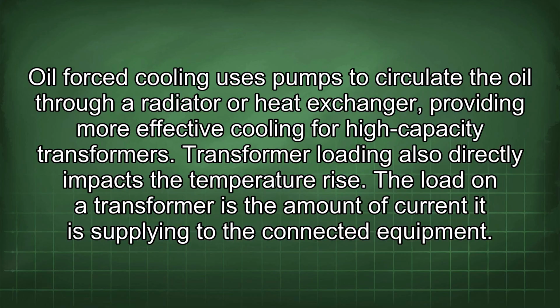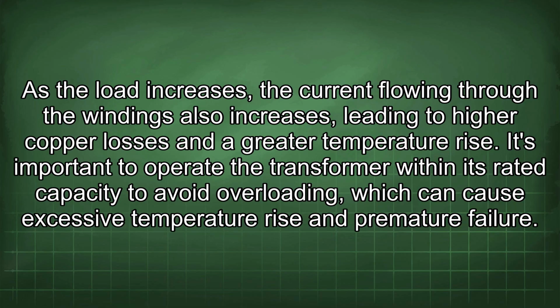Transformer loading also directly impacts the temperature rise. The load on a transformer is the amount of current it is supplying to the connected equipment. As the load increases, the current flowing through the windings also increases, leading to higher copper losses and a greater temperature rise.